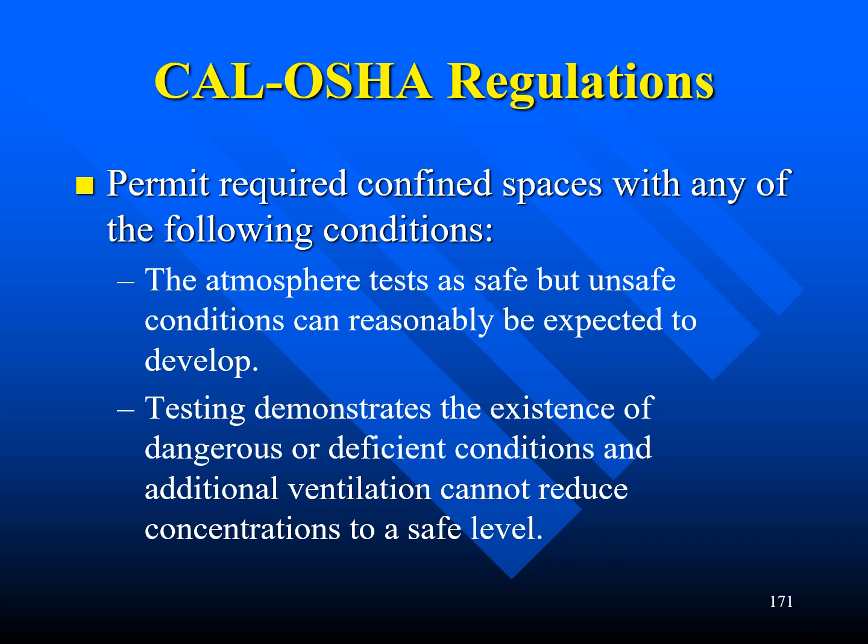Permit required confined spaces with any of the following conditions require communication. The atmosphere tests as safe, but unsafe conditions can reasonably be expected to develop. Testing demonstrates the existence of dangerous or deficient conditions, and additional ventilation cannot reduce concentrations to a safe level.